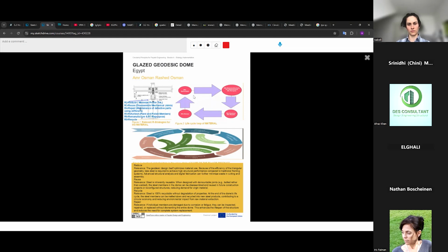This one here was a little bit more confusing with the life cycle material. I think it maybe hasn't addressed specifically the material itself, what's happening with the aluminium through the process. But what was good about this is that the detail is here, and you can see how this is mechanically fixed. Last time we were talking a bit about Durnell's project with the stick system and how that would come apart. I think it's quite similar to how this one would be disassembled, where it's all screwed from the top here.